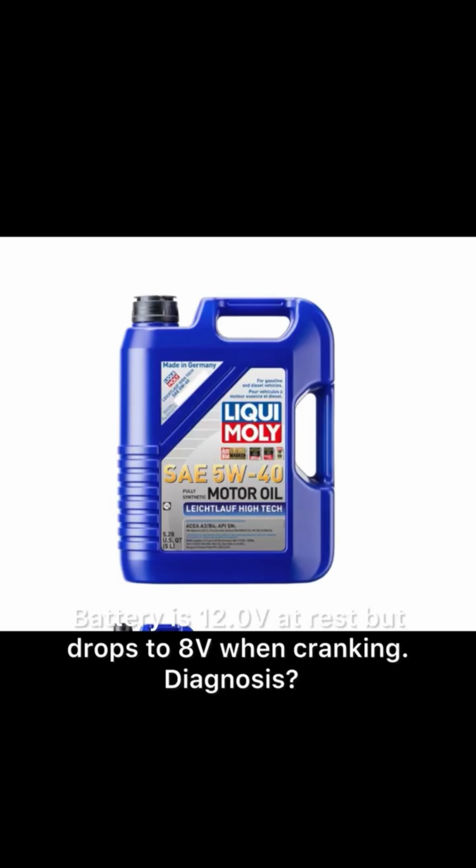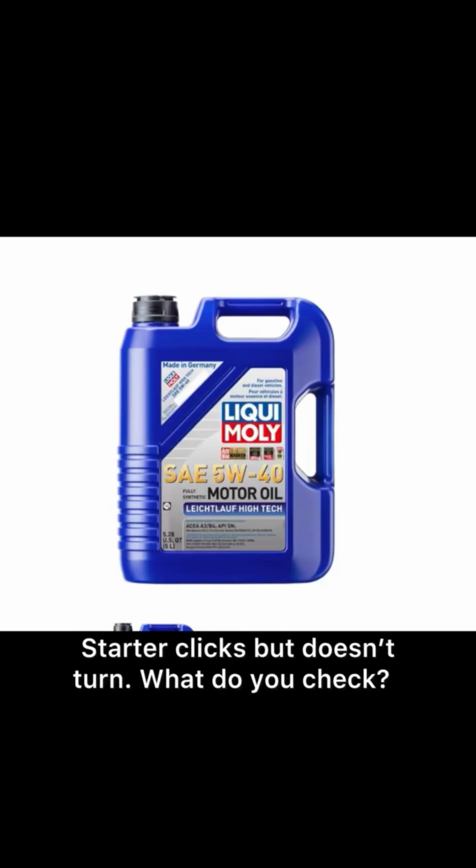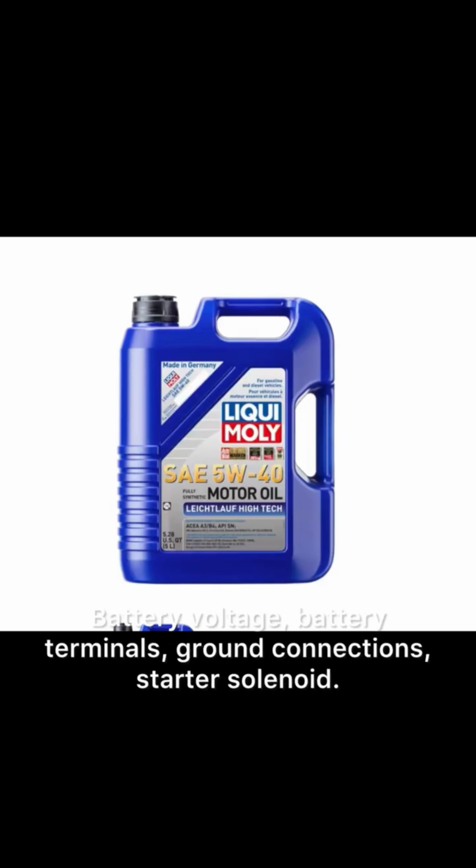Electrical and starting/charging diagnosis. Battery is 12.0 V at rest but drops to 8 V when cranking. Diagnosis: battery is sulfated/faulty. Fails load test. Starter clicks but doesn't turn. What do you check? Battery voltage, battery terminals, ground connections, starter solenoid.